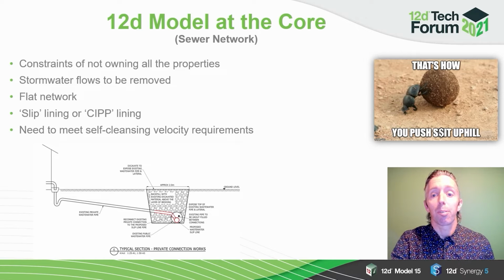The sewer network for a project is more complicated than usual. Because the existing network is combined, pipes are between 525 to 300 millimeters diameter. This was to cater for the increased stormwater flow instead of the usual 150 diameter pipes. The sewer network is laid at a very flat grade for a large portion of the network as well, and generally runs in the backyard of properties, sometimes under houses.